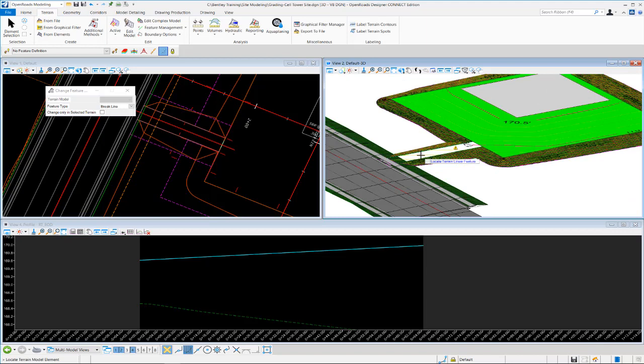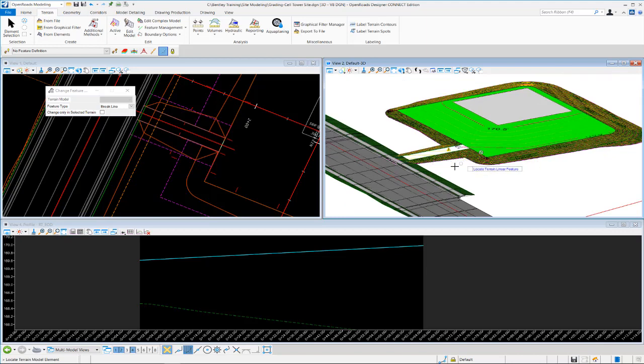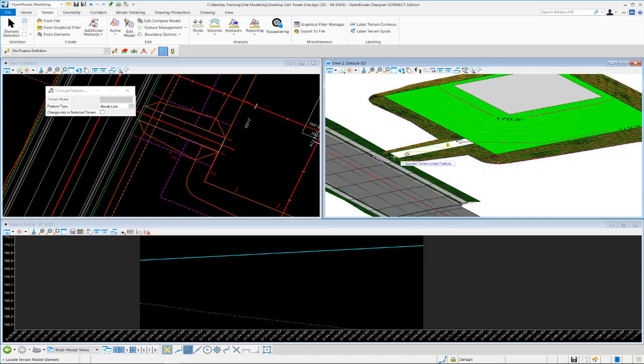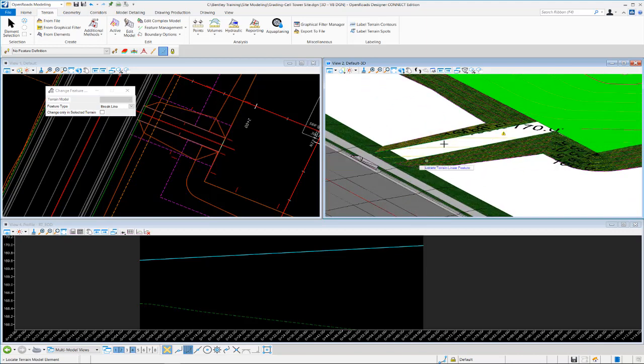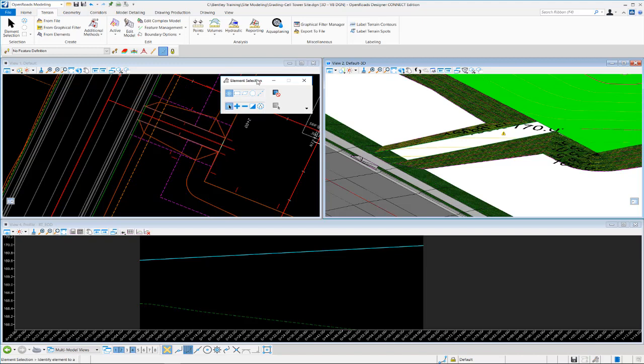So you can see we have the cell tower pretty much complete at this point, but we do still have some area of overlap here that we need to address. We can fix that by going into our side road corridor here and doing some clipping. We used clipping references over here; we did some corridor clipping to fix up these overlapping slopes. Now we're going to use that same tool and fix the overlapping slopes here, but we have to go into the other corridor to do that.